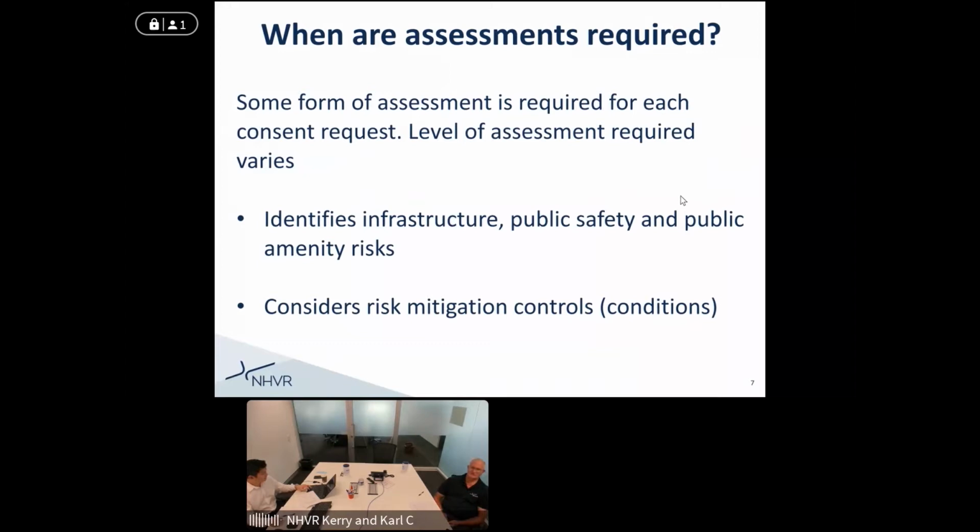If I'm moving a 200-ton transformer down a minor road with some suspect bridges on it, with mod prime movers and everything else, that would be a high level of assessment. So it depends on the level of assessment. Some are easy, some are hard. The idea is you get the easy ones out of the way by putting them into notices or doing pre-approvals, so you can concentrate your efforts and your time on the ones that have the greater risks.